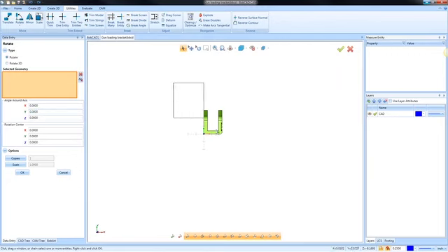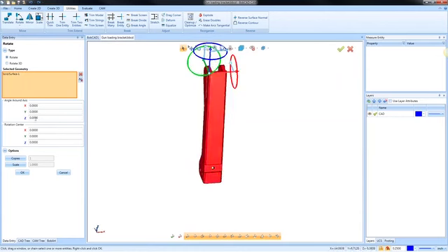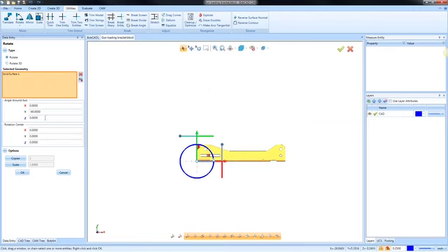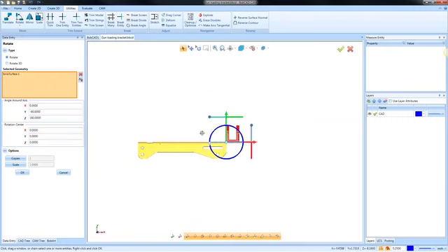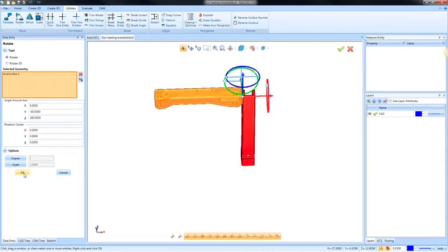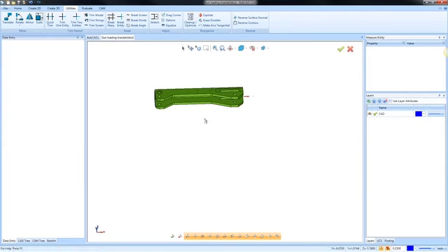All right, what I'm going to do is window pick this geometry. Okay, from here, I want to rotate it minus 180 degrees. Nope, let me see here. What do I want to do here? I want this to go minus 90 degrees to get it laying down flat in the XY plane. And then I want to rotate it 180 degrees in Z, so that way I have it facing this direction. Okay, I'll choose OK and cancel.